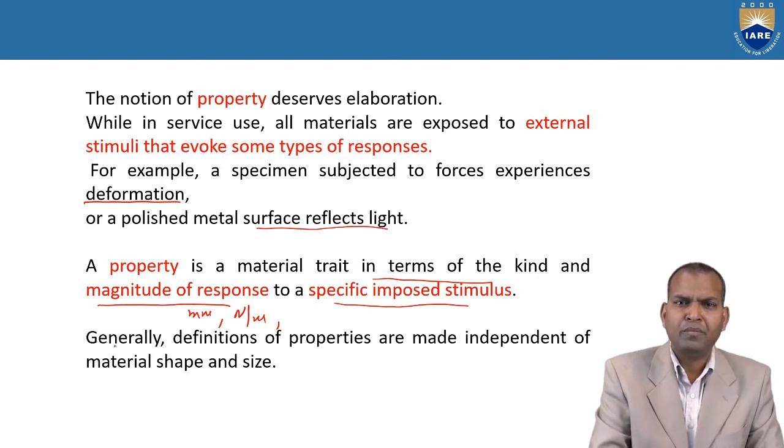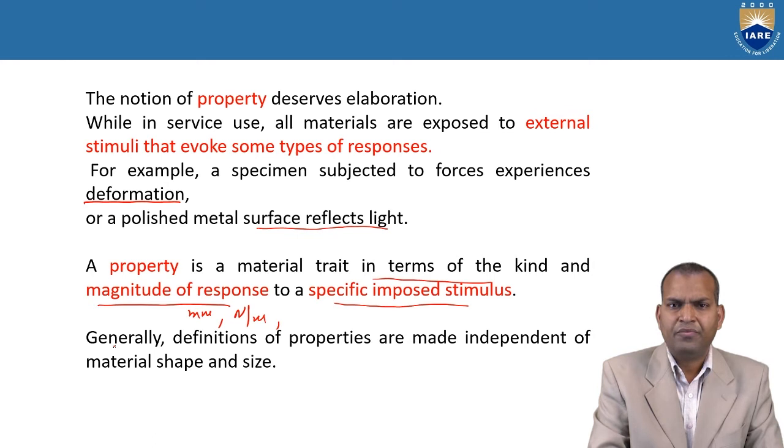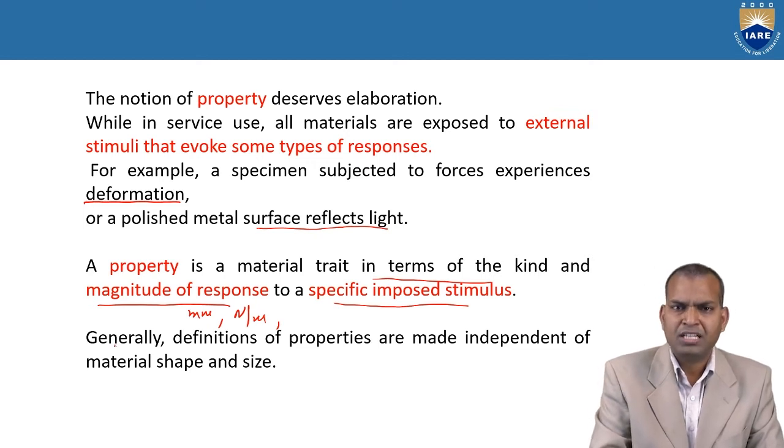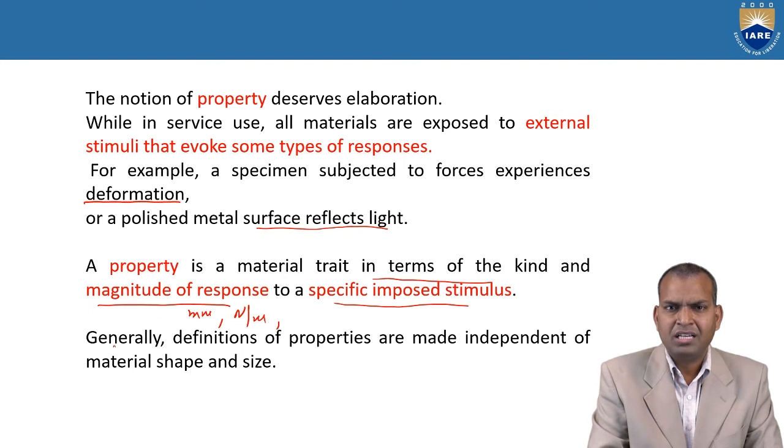So, in order to minimize this resonance phenomenon, in order to avoid resonance vibrations, what do we have to do? We have to operate the machine either above the natural frequency or below the natural frequency. So how can we calculate those? These natural frequencies can be calculated with the help of modal analysis.